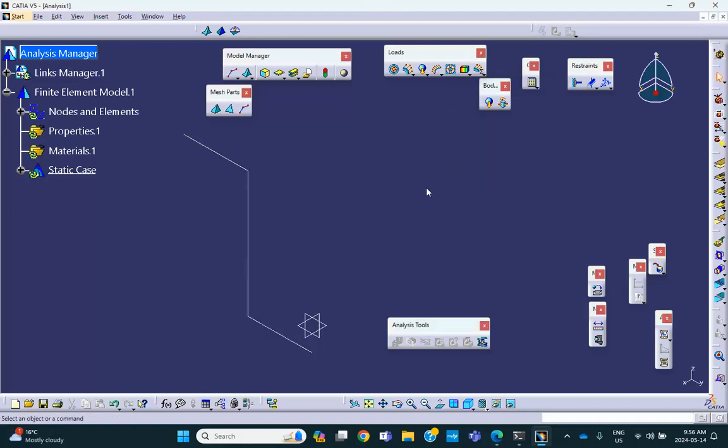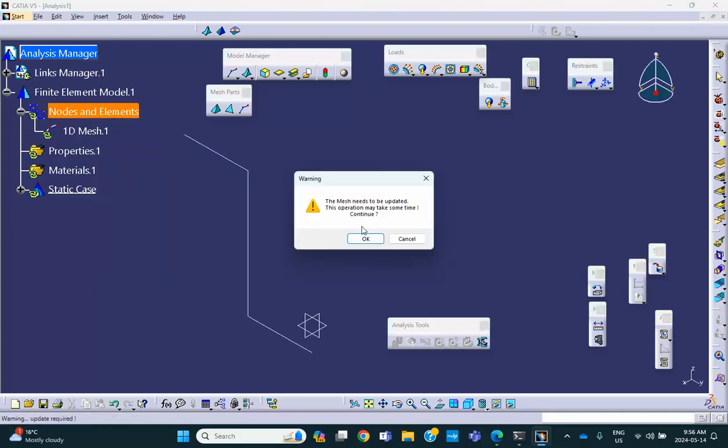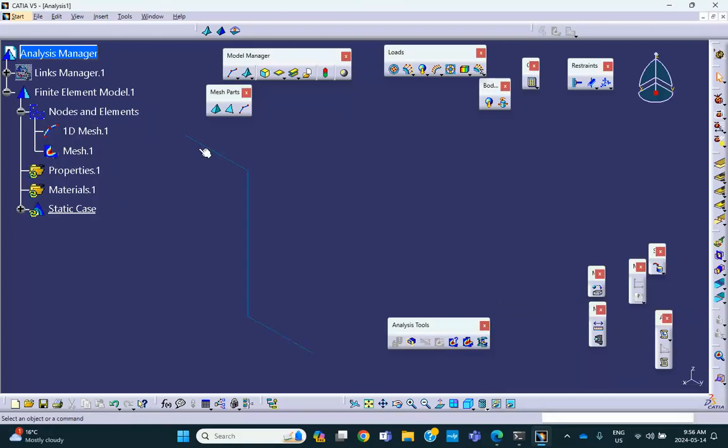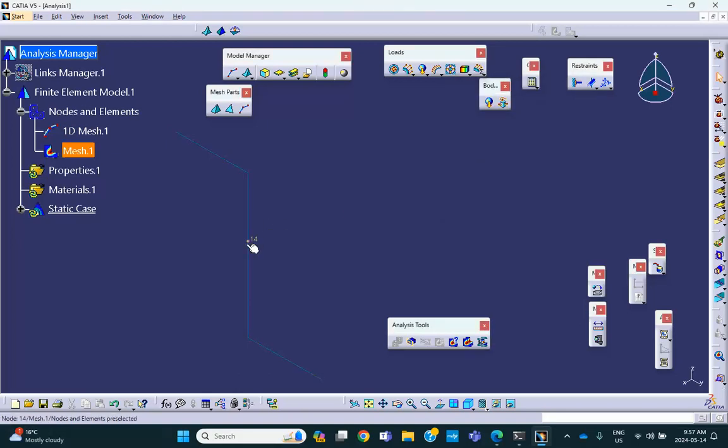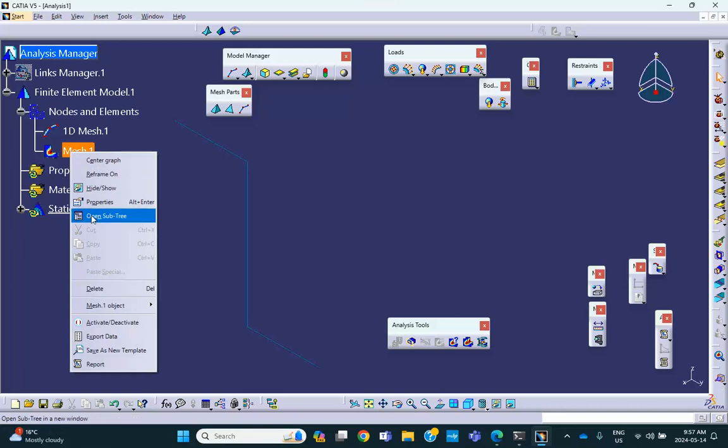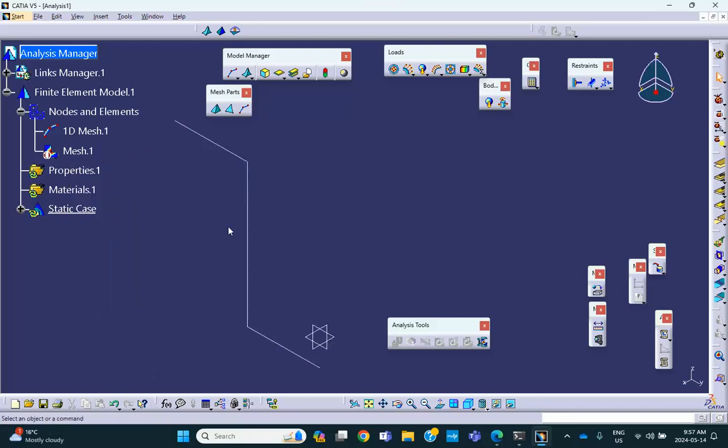Okay. And if you want to see the mesh, put the cursor there, right click, mesh visualization. And there you can see the type of the elements. Let me see what kind of element I'm using. I'm using linear. These are the 2-noded ones we should find. And so these are the elements and nodes, etc. Now deactivate this. Okay, so we meshed it.